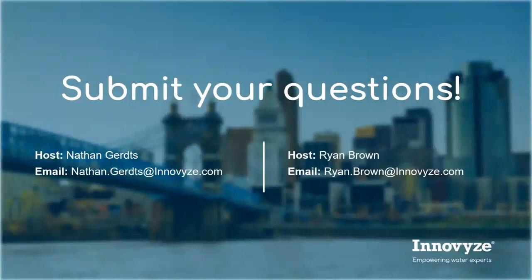You do have to buy the ICM suite, which I do believe. Don't quote me on this, but I believe Innovyze is offering that add-on at a reduced price this first half of this year, because we do want to see more people using that tool. But once you have that, it's all configured in a table. You can add sensors on the map like any manhole. You just add a point on the map.